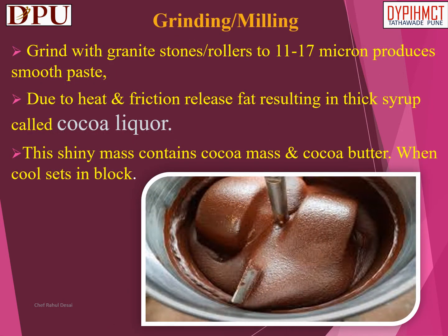Grinding: milling, grinding with granite stone rollers to 11-17 microns, produces a smooth paste. Due to heat and friction, fat is released, resulting in a thick syrup called cocoa liquor. This shiny mass contains cocoa mass and cocoa butter. When cool, it sets in blocks.